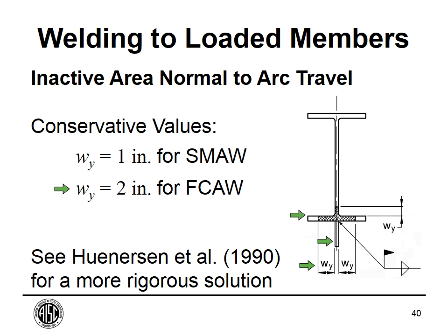Now for me, personally, I just use the section modulus. I don't use the plastic modulus, and the reason is because when this weld cools, I don't want there to be a kink in my beam where that beam has gone into the plastic range.